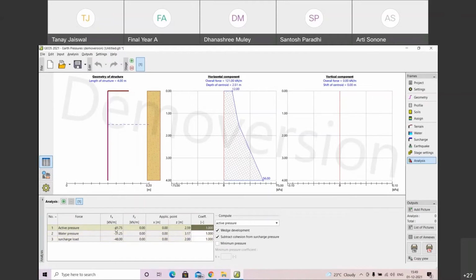So if you have BC Punmia, then you can see that active pressure is given as 41. It is negative because the pressure will be acting in the opposite direction, which is from right to left. Therefore, they have mentioned all the negative signs here. And you don't have to do any edit about coefficient of friction. In the earlier presentation demonstration, our senior Sanket Raut just edited the coefficient, but we don't have to edit it because the software takes the coefficient of active earth pressure into account in itself when we put the angle of friction. So there is nothing to change here.